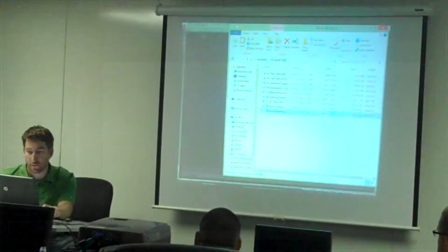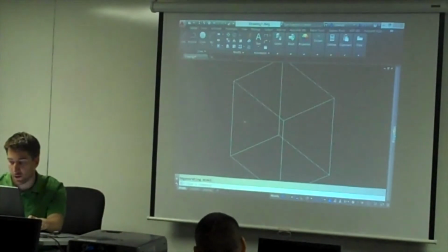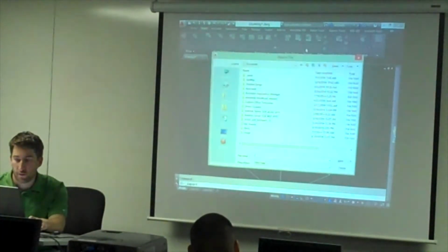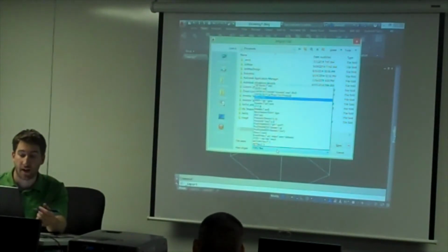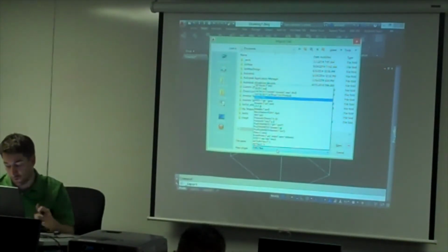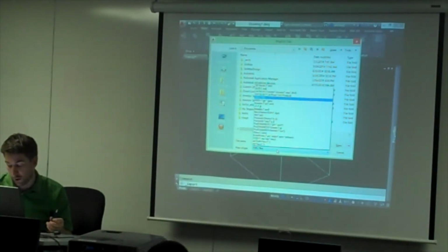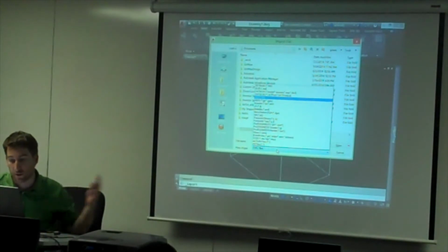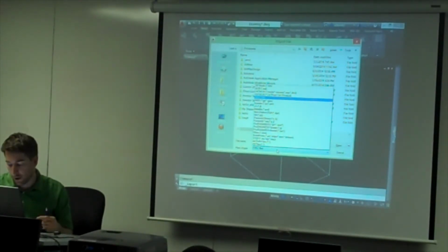Other things that they didn't cover that I thought might make some sense to interject here real quick. So they've added some more flexibility in terms of getting different types of data in and out. They have this new thing called the Autodesk Translation Framework, and it allows you to import model data from different manufacturer file types. So you've got your SolidWorks, your Pro E, DGN, STEP files, CATIA, and some others.